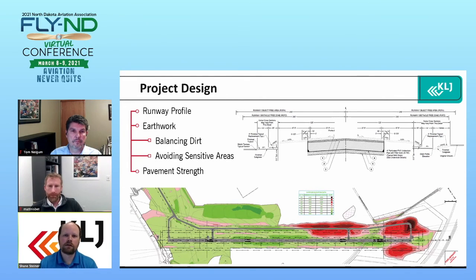And really looking forward into the future, going back to what the airport wanted, is to be set up for the future, so that in 10 years, if the aircraft were using the airport that they projected and that local businesses were saying they were going to be coming in or utilizing, we didn't want to be short. So what we ended up doing is bidding two sections, an 8-inch concrete section and a 6-inch concrete section.